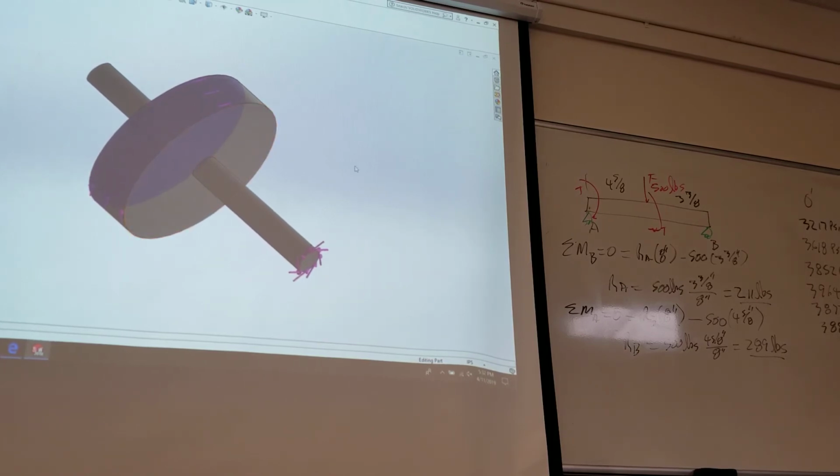And I'm going to need the torque on the end, but I'm not going to need the torque here on that guy. I'm just going to need the one on the end here. And so what we're going to do is we'll get our fixture, do our advanced fixture. I'm going to fix this outer ring here. I could fix probably anything. It doesn't really matter. This thing's such a big chunk of metal. Anywhere I fix it, it's going to do this thing. I'm going to use as a reference geometry my same face, and I'm just going to lock it all up.